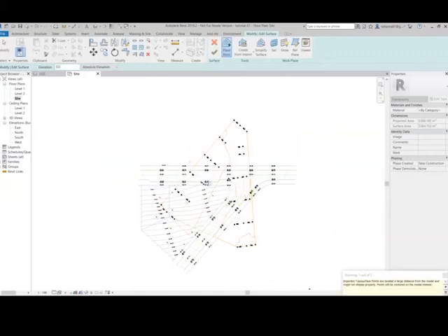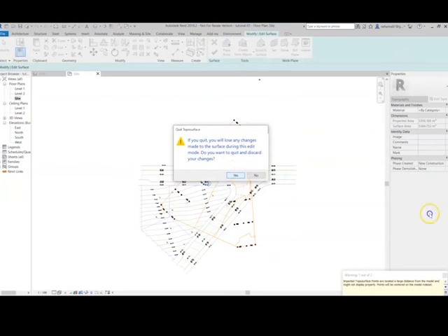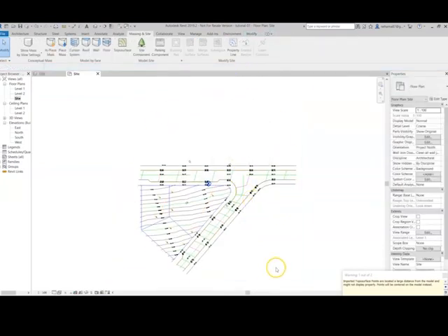And now you can see that Revit has a warning. Imported topo surface points are located a large distance from the model and might not display properly. Points will be centered on the model instead. So basically Revit tells us that it's not located in the right coordinates. If it's important for you to work on true coordinates, you have to do it another way.